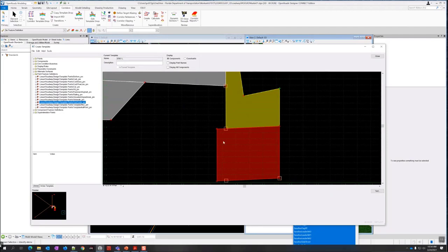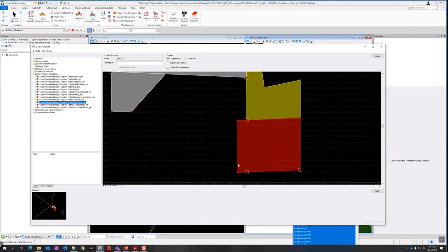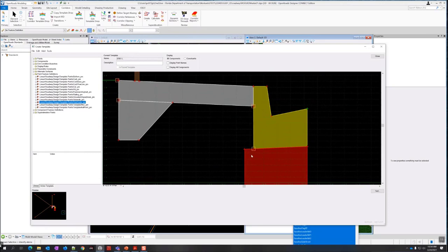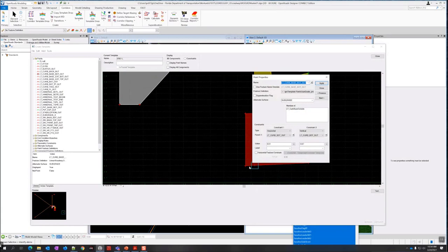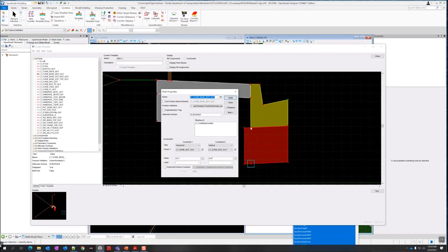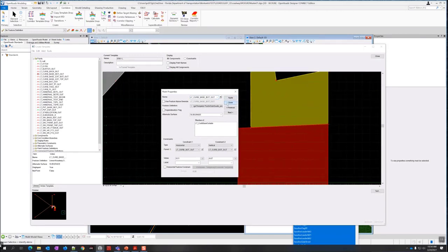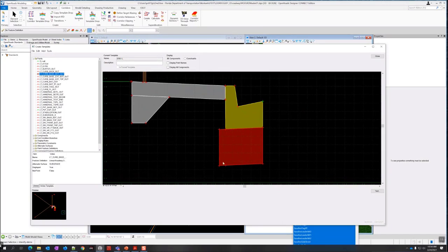But this is a good example of where you'd create a cave, okay? So if I did subgrade all the way out to here, and then subgrade all these points, no, that's not going to work. It's not going to know how to triangulate here. So what we're doing here is we're coming to this point right here. If I edit it, you can kind of see it. Here's my 0.01 offset from the curb bottom out. So it's 0.01 in. And you have to make sure it's in the right direction. It needs to be 0.01 to the right here so it'll slope out this way. It'll make a nice gradual slope.